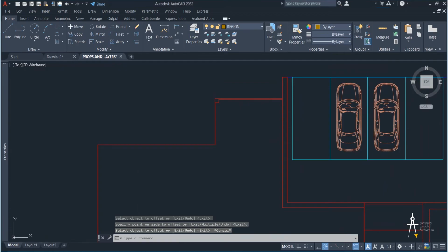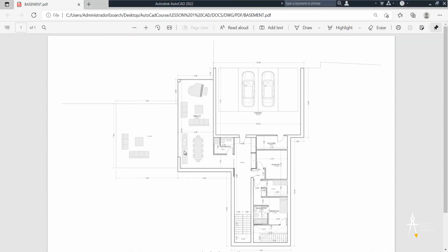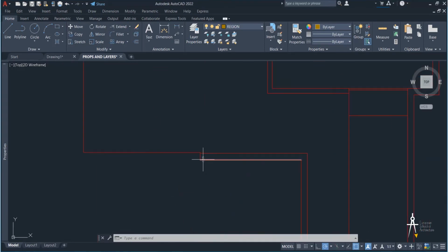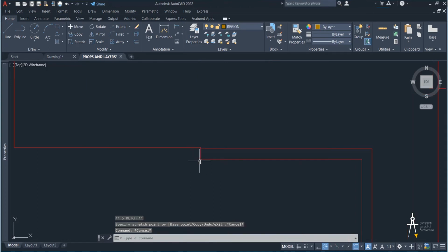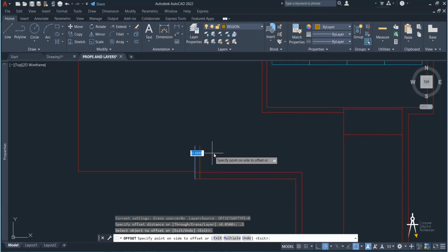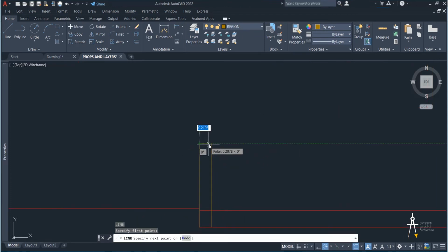How does this work in our plan? Well, we take it all over to this edge. It doesn't specify how long this is, but let's say it's 2 meters, something like that. It's not important. So maybe we can say up to this point 2 meters. Just going to say L and 2. Offset 0.3, and then a line joining them.